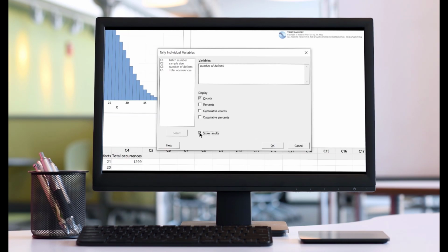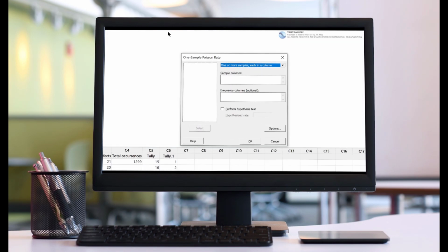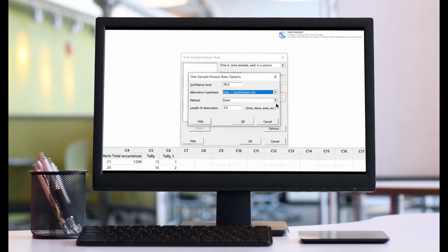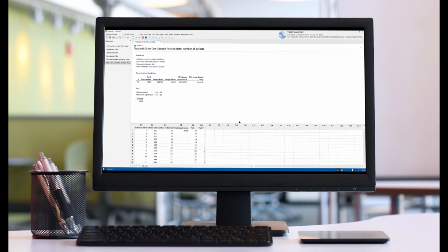The central topic in this Minitab tutorial will therefore be to make a 95% reliable statement regarding the actual defect rate in the population of shock pad production on the basis of an existing sample data set. We will learn that hypothesis tests that follow the laws of the so-called Poisson distribution can be used in such cases.